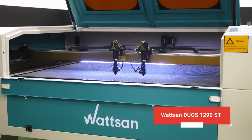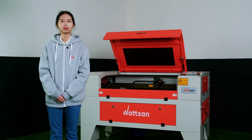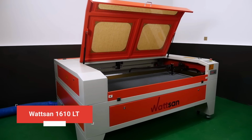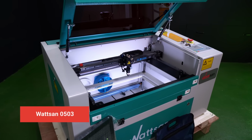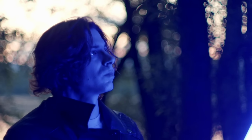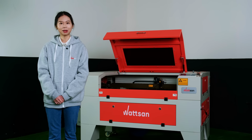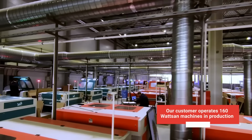Machines with a larger working area are typically equipped with more powerful tubes. The larger the lens diameter, the more heat it can withstand. That's why the lens for a 1610 machine with a 120 tube will have a diameter 20. However, on a 0503 machine with a 60 watt tube, such large diameters are unnecessary. Why would you need a lightsaber to cut an apple? Cool? Sure, but expensive and completely impractical. Wattsan operates on the principle of adequacy.